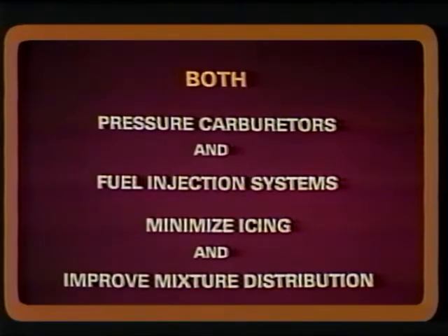Pressure carburetors and fuel injection systems perform these same functions in a little different way. In addition, they are less susceptible to the formation of carburetor ice than float carburetors, as well as distribute a more uniform fuel and air mixture than simple fuel metering systems.